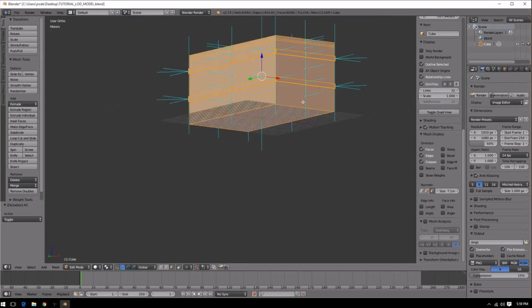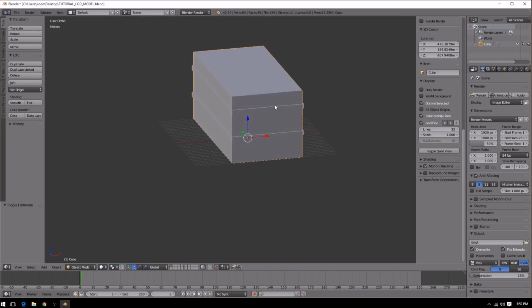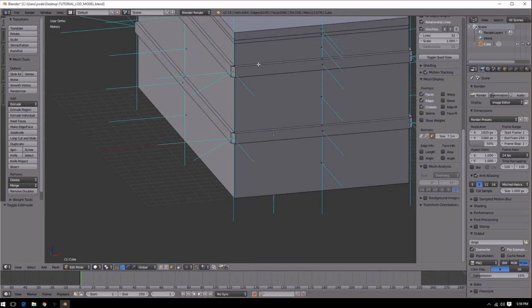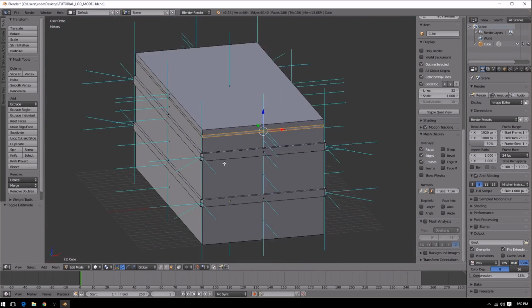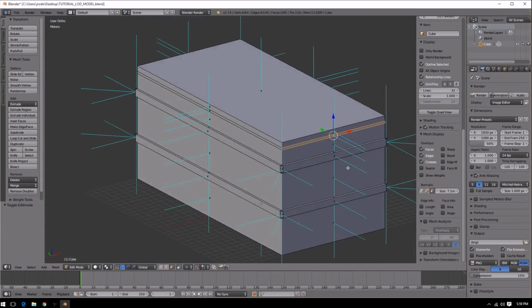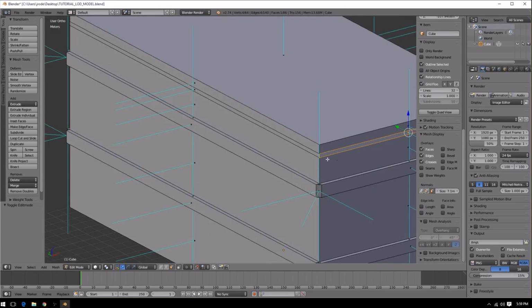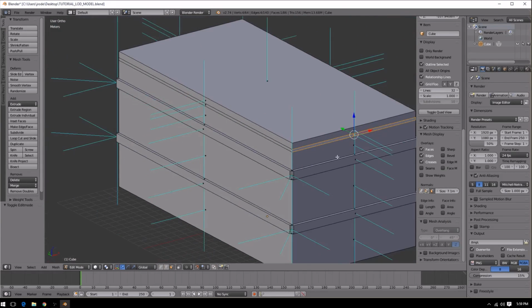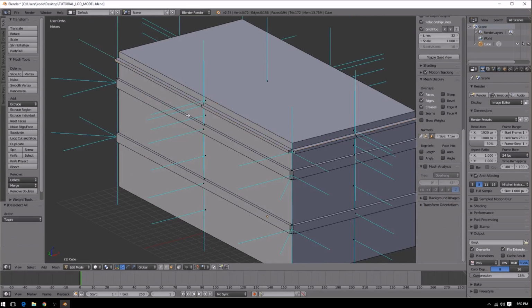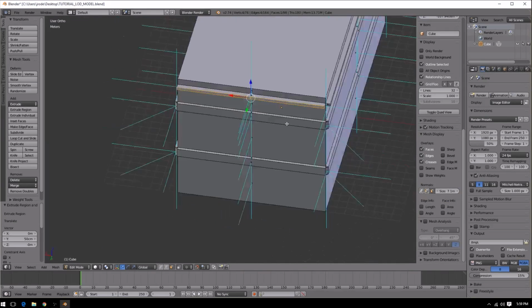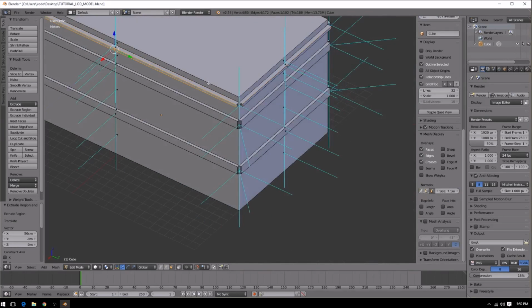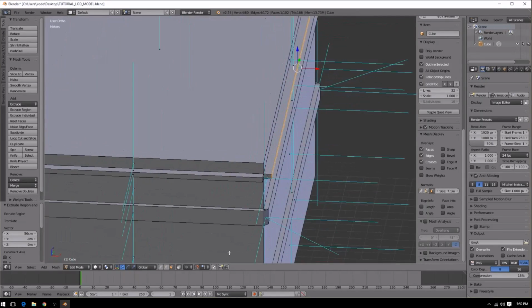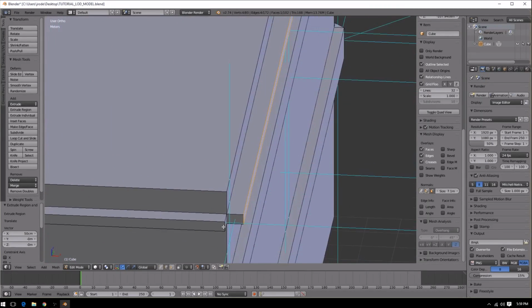Okie dokie. So now we've got this set up, and we've got these basic borders here, and that's kind of what I wanted. I didn't want this building to be a flat building. So what I'm going to do is go back to these top portions, and I want to extend these a little further out than these ones. So these are going to go out 0.5, but I'm going to extrude these 0.5 and do the exact same thing I just did with the lower ones. Okay, so again, the tedious process of selecting these and doing this again.